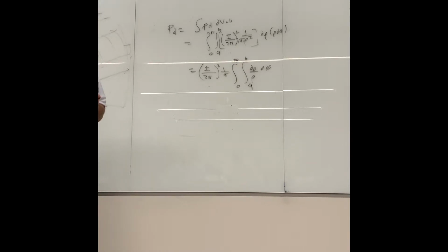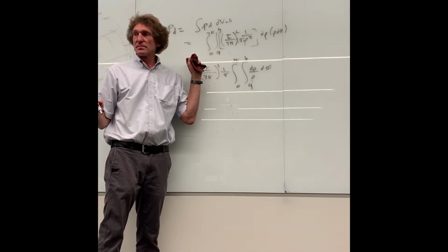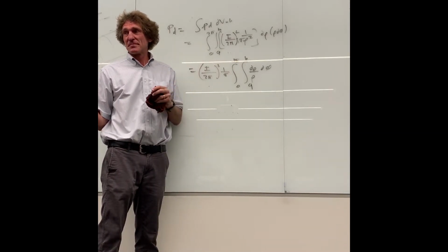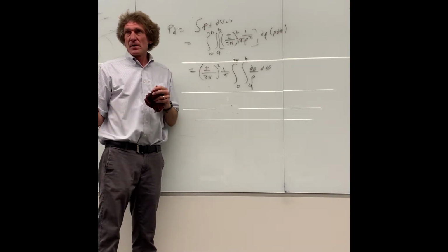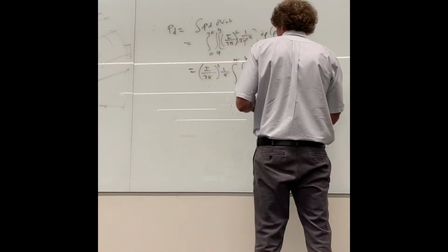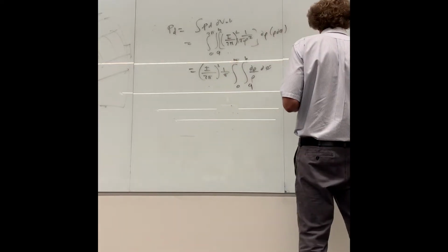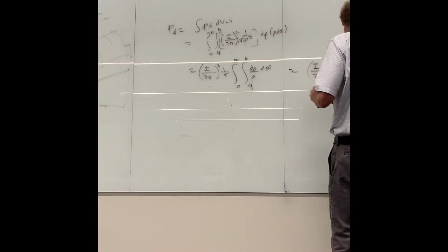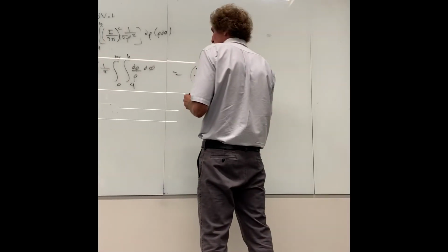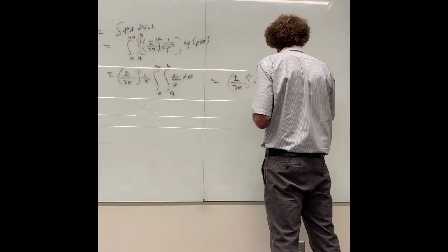What happened, are we getting rid of the third integral? Well, remember that's dz, right? It goes from 0 to 1. So it doesn't change. From 0 to 1 is 1. dz is just 1, so I ignored that. Now, what is this going to be? Well, the I over 2 pi squared is here, right? I have 1 over sigma, that's still fine. When I integrate d phi from 0 to 2 pi, I get 2 pi. Then when I integrate 1 over rho from A to B, I get natural log of B over A, correct?